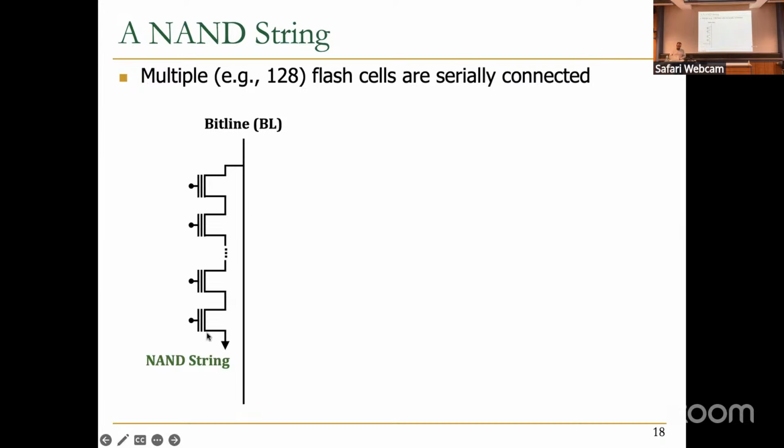So now the connection is actually very much limited. Between all these NAND cells, we have only one connection here to the bit line, right? Which means that it will reduce the bandwidth, or it will increase the latency when you want to read from a specific NAND flash cell. But in NOR flash, they provide much more connectivity, so it's much faster. But the problem is that NOR flash is less dense. Because of that density and performance trade-off, most of the products that we have nowadays use NAND flash memory.